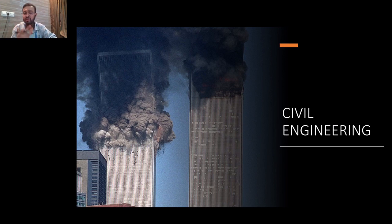Now this fuel burnt and burnt and burnt, and that is what you can see, the flames which are here. And that caused the metal structure, which is part of the building, to slowly soften because of the heating which is taking place because of the burning fuel. And as soon as that happened, the entire building basically started buckling, because at a higher temperature the properties of materials change, the materials start to soften, and so on and so forth, and that caused the entire vertical part of the building, the above sections of the building, to force it down and cause it to buckle. And you can actually see that happening here.